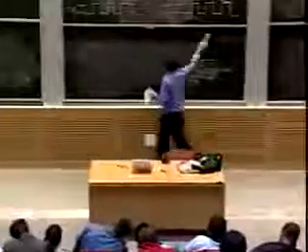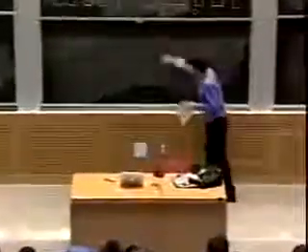This time shifting leads to these kinds of problems where we don't properly decode the message, because we're not sampling the channel at the right point in time. We're not looking at the channel to see whether it's high or low. Okay, so how are we going to fix this? It turns out that there's a simple and elegant way that's often used to fix this. It's called a phase lock loop, or a PLL.